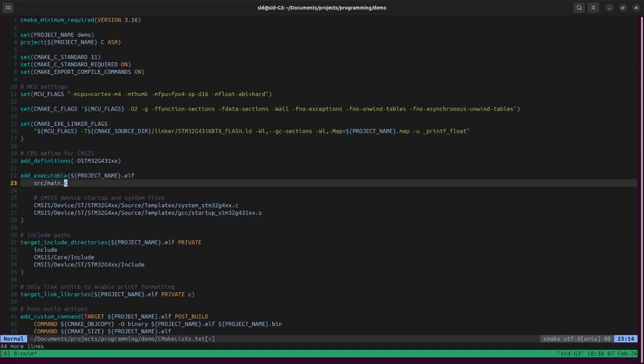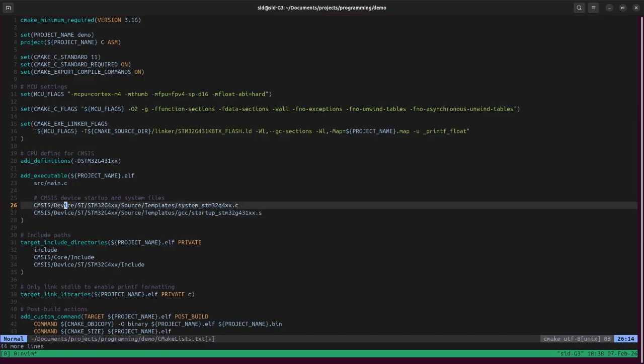And then we're going to start off with creating just one main file, since it's more of a setup project. So it's going to be really simple. I guess it's just going to have a main.c, and these two lines here are really important from the CMSIS folder we copied. You have to link these two as well. This assembly code as well as this startup C code.